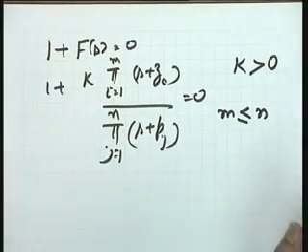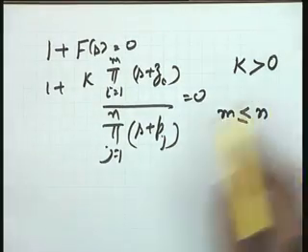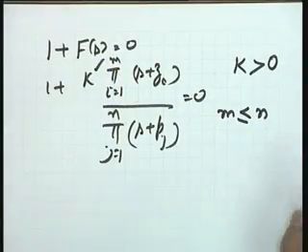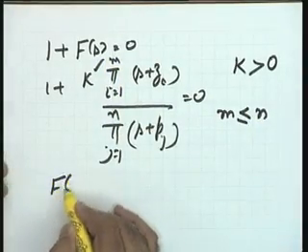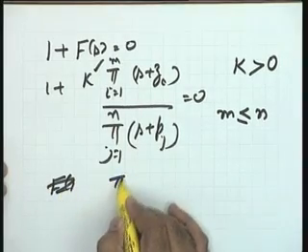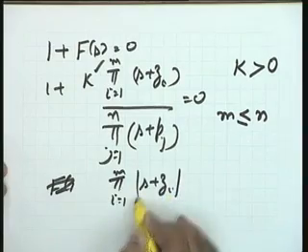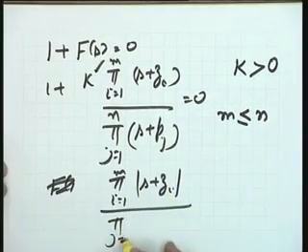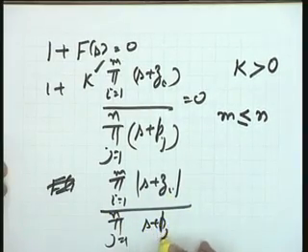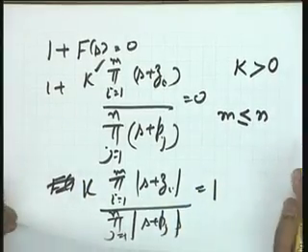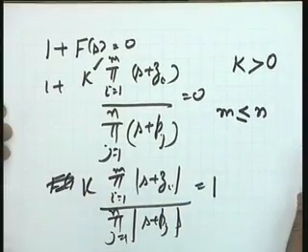Okay. So this is the situation. I want the root locus plot of this particular system as k varies from 0 to infinity, and you recall that the equations available with me are: the product over i equal to 1 to m of magnitude of s plus zi, divided by the product over j equal to 1 to n of magnitude of s plus pj, into k, equal to 1. This is your magnitude criterion or magnitude condition, and the angle condition is going to be